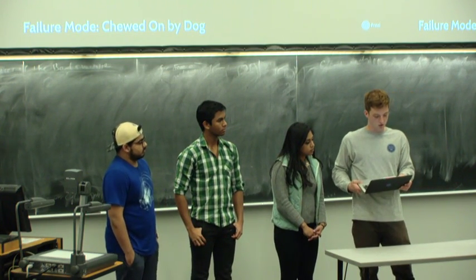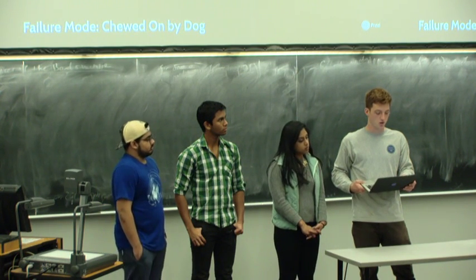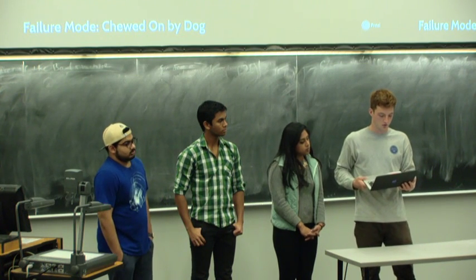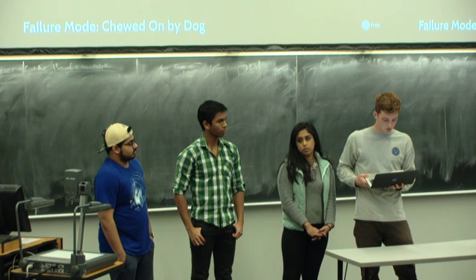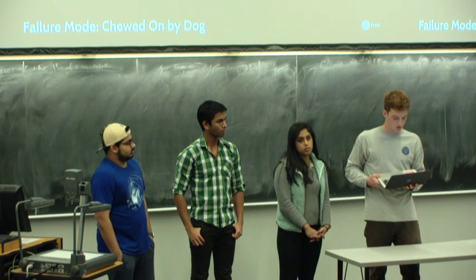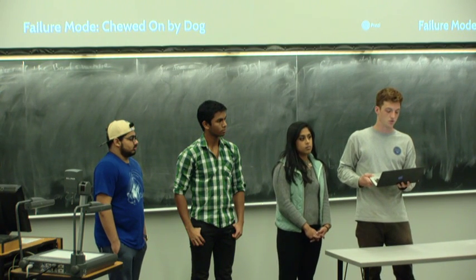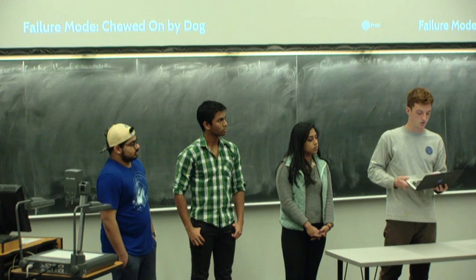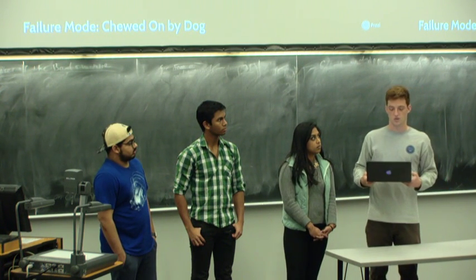Okay, so then the material selection or inspection failure was the potential cause. So someone at the company may not have checked this material correctly. And the occurrence, we gave that pretty low, so we gave that a 2. The current process controls, we said that the operator needs more training or better instruction. So the detection on that would be a 3, and that gives an RPN of 54, which was low enough to where we didn't recommend an action.